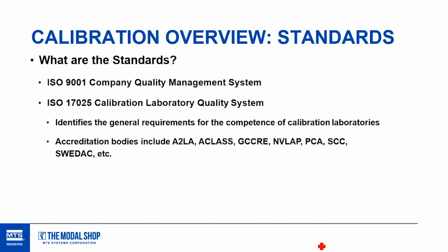There's a lot of accreditation bodies that will go on site to your facility, or to whatever facility is doing the calibrations, and audit you for your ability to deal with issues that might happen during a calibration, make sure that you're reporting your uncertainties correctly, make sure that your certificates are set up to convey all the relevant information for an ISO 17025 calibration.